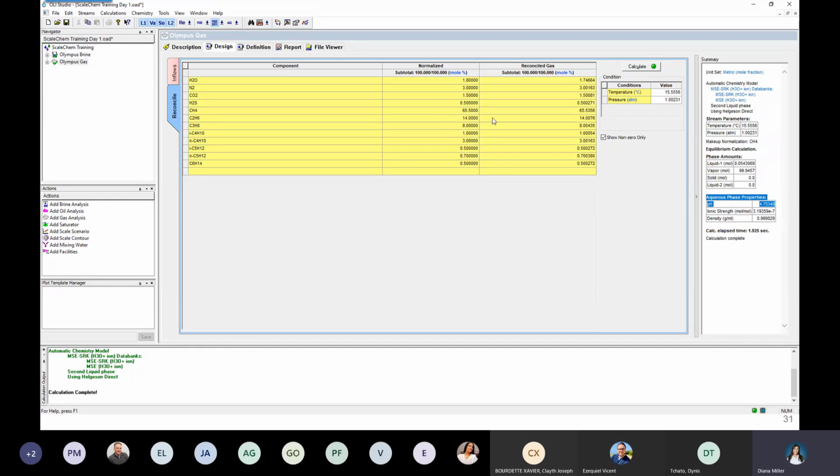And these gases will dissolve in the water phase, and these acid gases will contribute to the acidity of the water. That's why you probably are seeing this pH value of 4.8 for the condensate that is being created in this gas analysis.